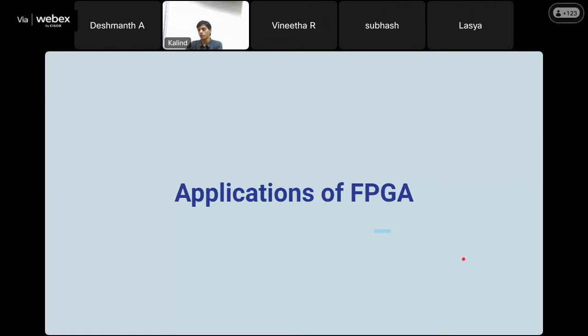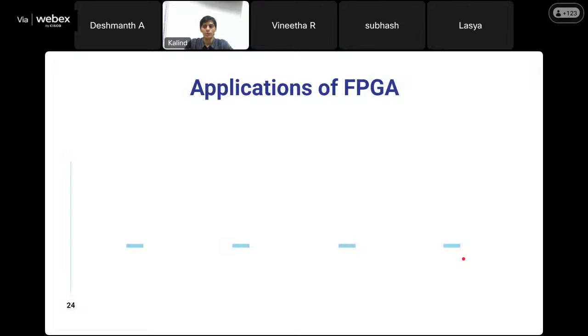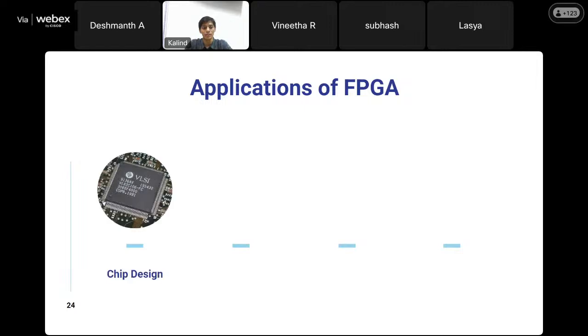Let's talk a bit about the applications of FPGA. We'll talk about four major applications, but of course it is not limited to these four only. There is a plethora of applications in the world you can implement using FPGA. One, as I told, is chip design. You can realize the entire logic circuit of your chip on FPGA, make sure it is working fine and meeting the functional as well as the timing specifications of your input design, and verify that.